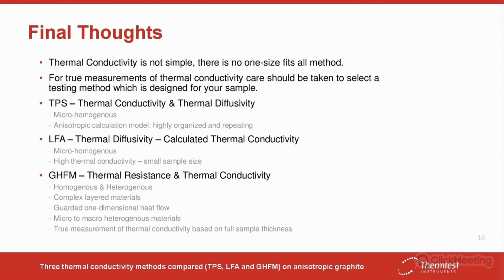The other thing to keep in mind when using the TPS for considering your full thickness is that the reported penetrations with these methods are based off the accuracy of the diffusivity reported within the method. And that accuracy of the diffusivity is based off of satisfying some measurement parameters. So you can have error in your diffusivity, which will give you potentially misleading penetration depths. There really are some critical phenomena to keep in mind when measuring anisotropic materials that are non-repeating.